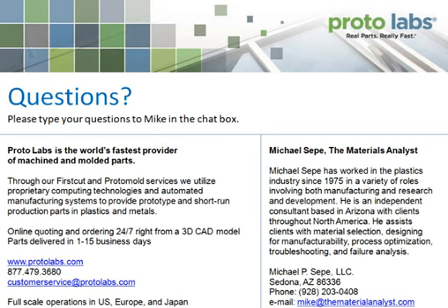Not only did we not have to invest in the pumps and the handling equipment for the liquid, but we actually did see better incorporation, which means fewer swirls, when we used color concentrate than we did when we used liquid. And some of the people I was working with who were also running the same experiments had the same experience. Now, again, this goes back a long way.